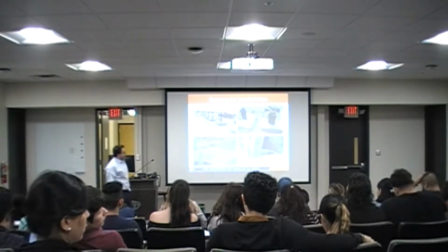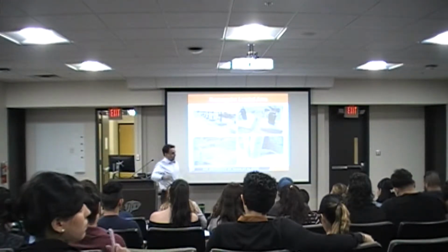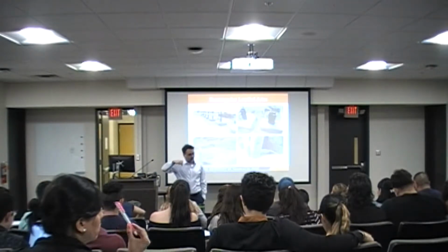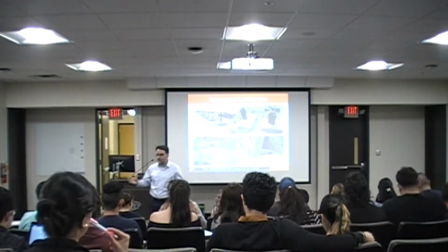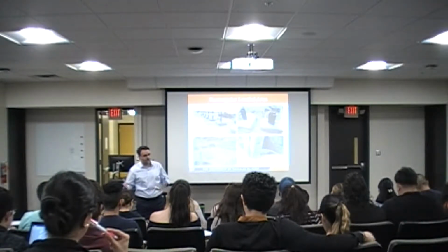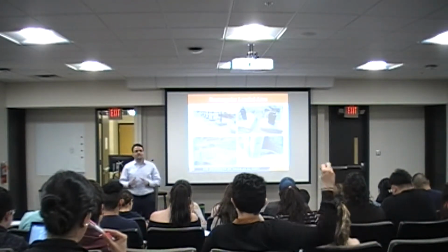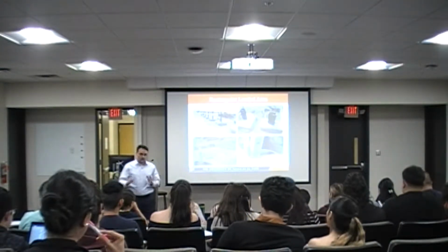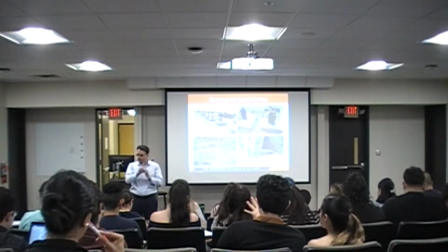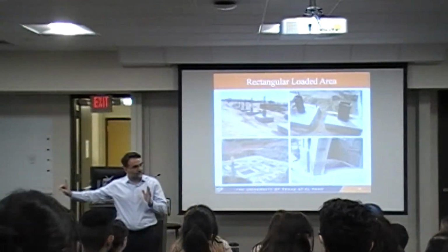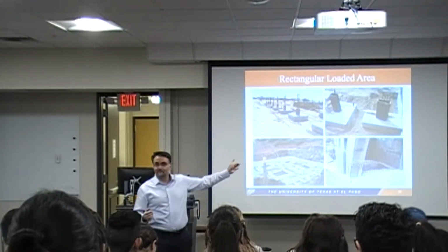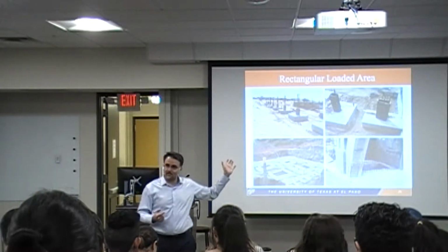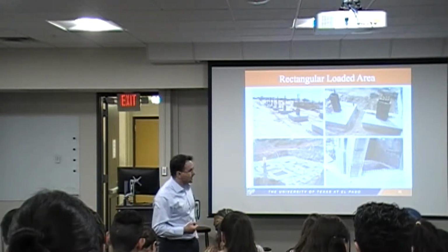All right, so that's what we have in terms of the general concept that we have to talk about when we go through. All right, we talked about the Boussinesq theory. Remember, Boussinesq theory considers a point load, right? Now, if you want to determine the distribution of the stresses for other types of geometries, what should you do? You have to integrate that, right? So if you're looking at the line load, you basically integrate that point load along the line. How about if you're looking at a rectangular shape? A typical foundation that you see, which is similar to what you see in this slide here.